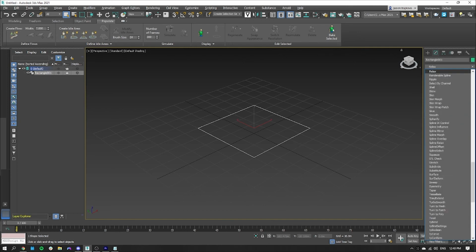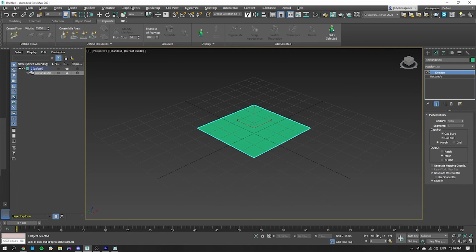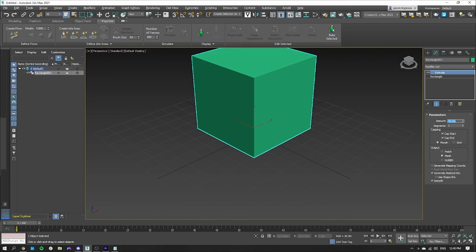So we'll go extrude, which you can either type in or search. Sometimes if you miss the letter, it won't come up. But let's go down to E, which is here, extrude. And there you go. It comes up with your shape. Here you go, you type in the amount. So let's go 50 high, and that has created a box.